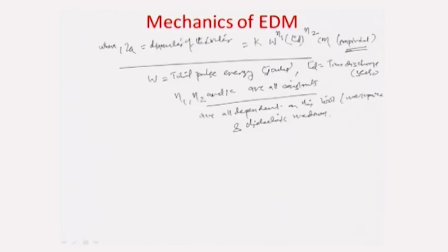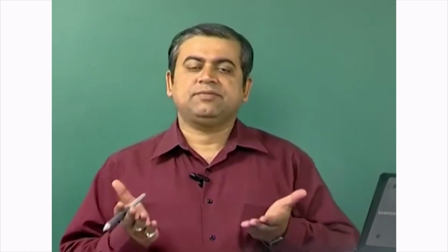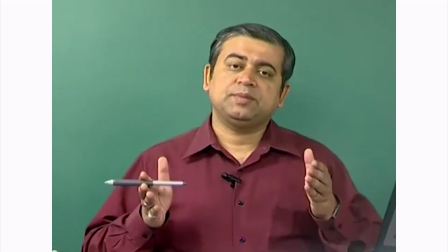We found out last time that the amount of heat of latent nature is estimated by assuming a cylindrical size of the cavity, although it is actually a quarter spherical size of the cavity. So, let us also try to estimate the volume of such a crater, so that a more accurate form can emanate out of the total heat which is needed for the depth of melting temperature analysis.